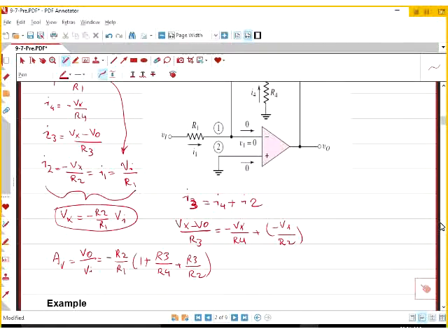But let me put it this way. We said the inverting amplifier works fine. It's good. It's only 2 resistors, 1 op amp, you are done. You can amplify any signal. But if your gain is too high and you want a high input resistance, R1 high, you're going to end up with a large R2, right? Large R2 generates noise in the circuit. So if you're an electronic designer, you don't want to use 5 mega ohm, 10 mega ohm, 2 mega ohm, no.